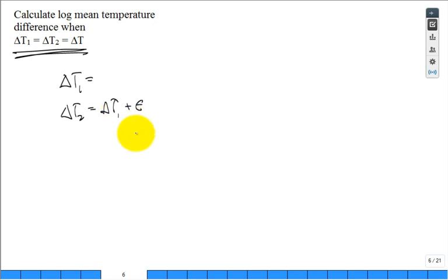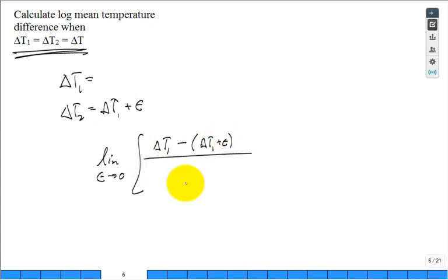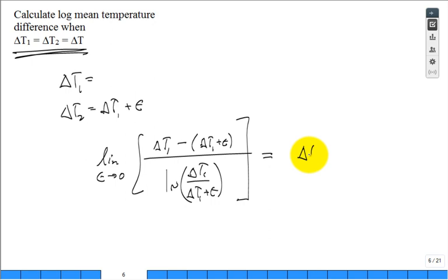And what I should find is the limit as epsilon goes to 0 of my log mean temperature difference, which would be delta T1 minus delta T1 plus epsilon divided by the natural log of delta T1 divided by delta T1 plus epsilon. The limit of that as it goes to 0, L'Hopital's rule, is going to be delta T1. There's a few steps in this...